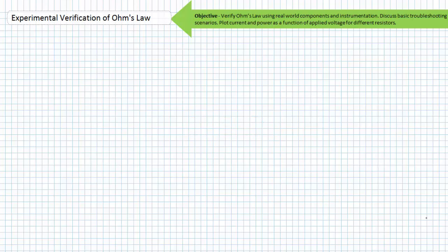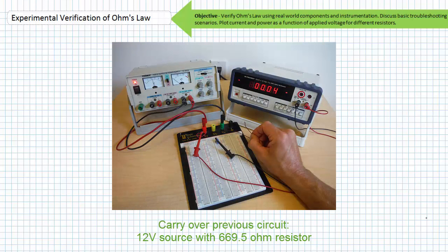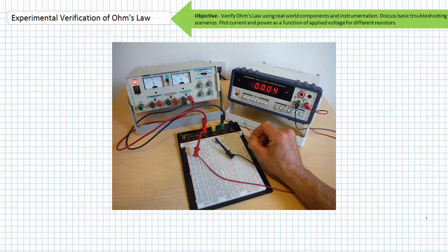regardless of its source, whether it's an errant open switch, a disconnected wire, or an improperly placed instrument. An open circuit will not allow current flow. If there is no current flow through an element, there will be no voltage drop across an element. This being said, if the source is on, there will still be a voltage drop somewhere in our circuit because there is a voltage rise, and therefore there must be an associated voltage drop. If there is one and only one open in our circuit, the voltage drop occurs at that open.